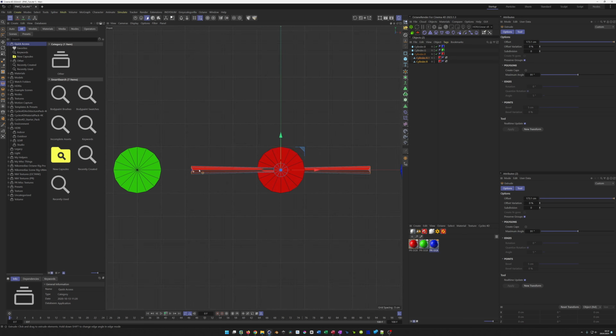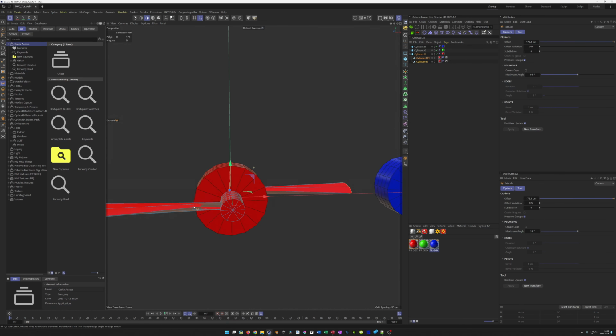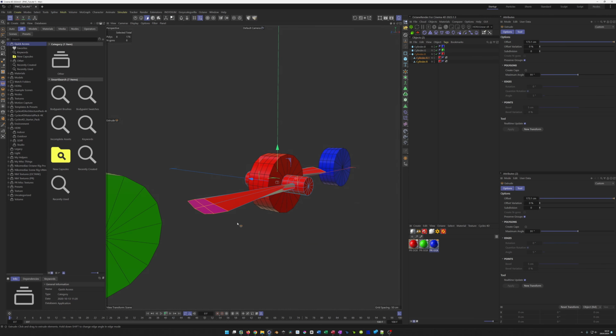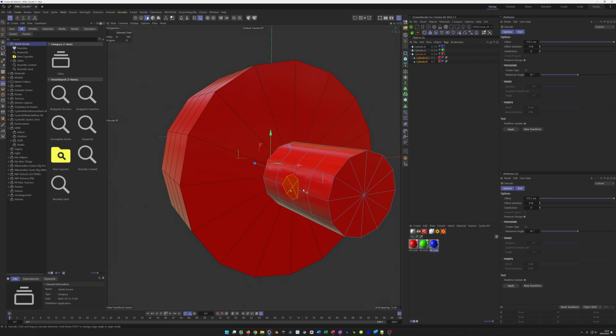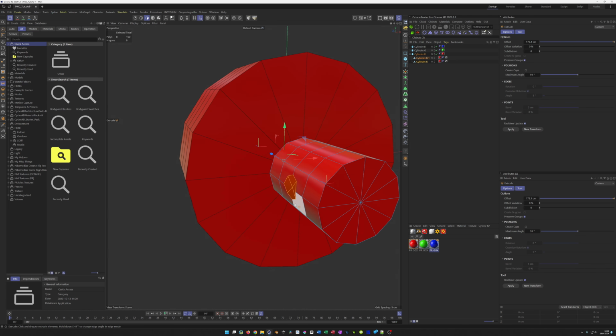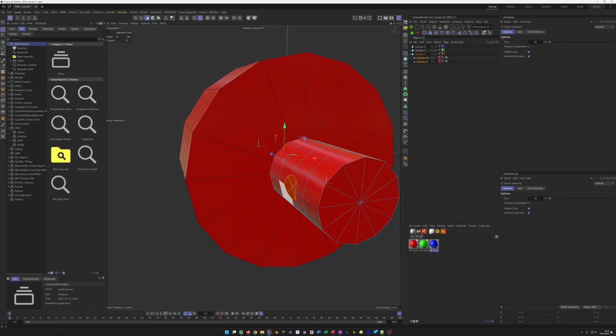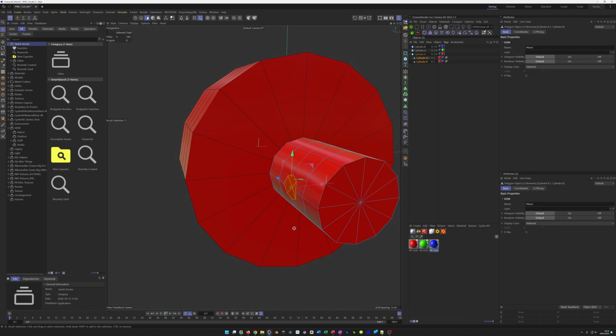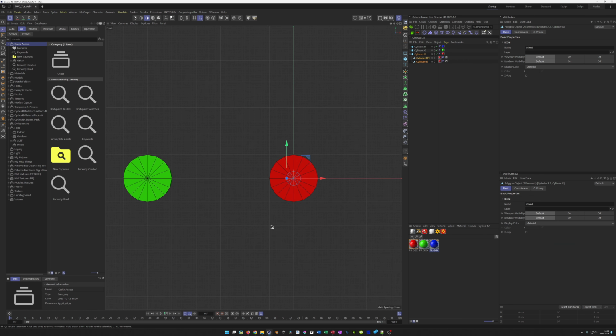But you see, that does not look correct because this was not totally flat here. So go back here. So what I do instead of extrude, I select just one of these, hold my control key and drag it to the side. Now it works perfect. And I hold my shift key, so let's say 250 that it intersects with this.